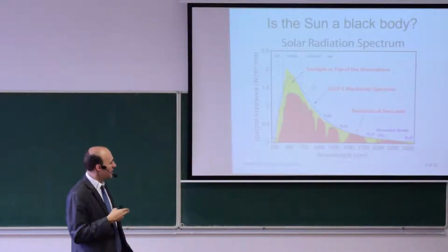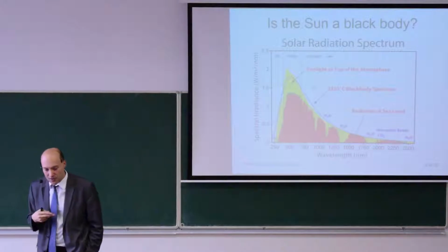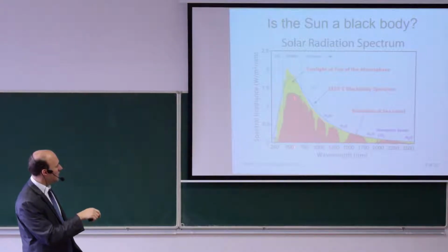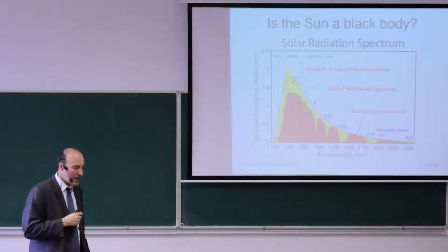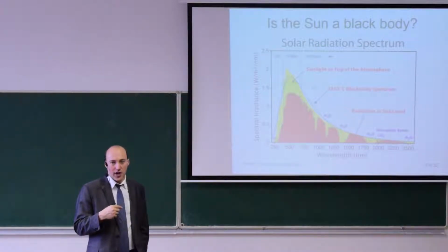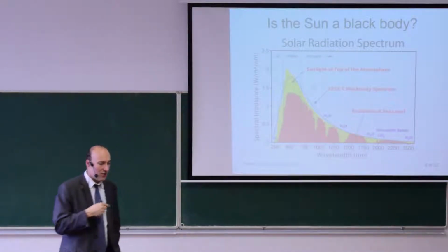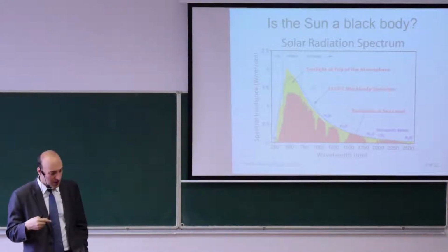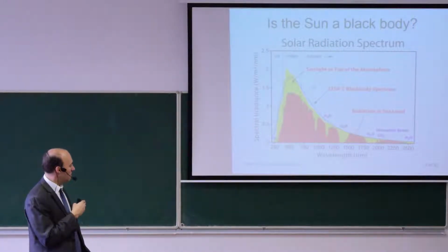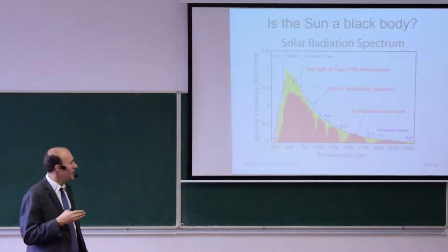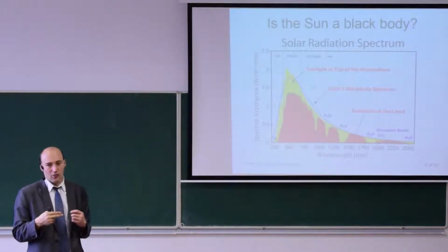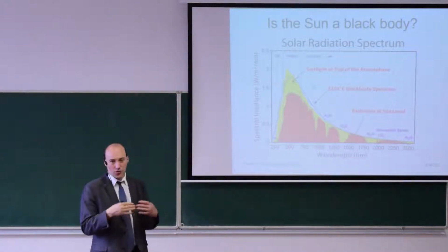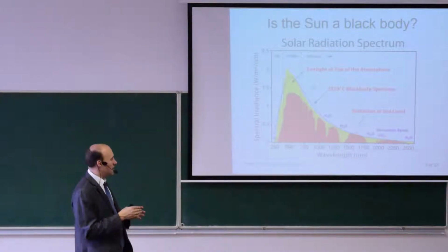So we will see that there are different types of detectors. Some work on one wavelength, for example, here 650 nanometers, and we are trying to compare the amount of radiation from my object on this single wavelength with the amount of radiation from some black body at some temperature. And some other detectors will work in a very broad range of wavelengths, and they will give us the total amount of energy that they receive. But in all cases, it's quite influenced by the absorption between the sensor and the object.